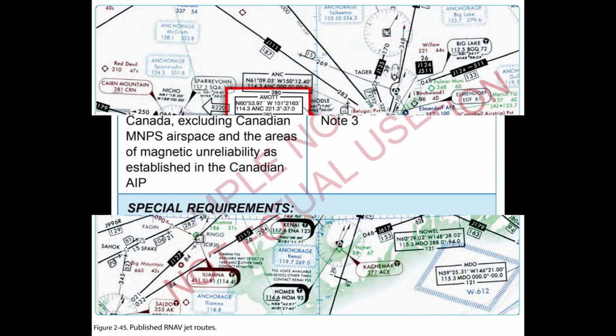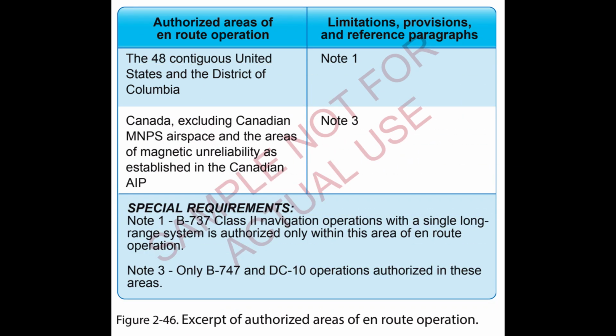Off-airway routes. 14 CFR Part 95 prescribes altitudes governing the operation of aircraft under IFR on federal airways, jet routes, RNAV low or high altitude routes, and other direct routes for which a MEA is designated. In addition, it designates mountainous areas and COPs. Off-airway routes are established in the same manner and in accordance with the same criteria as airways and jet routes.